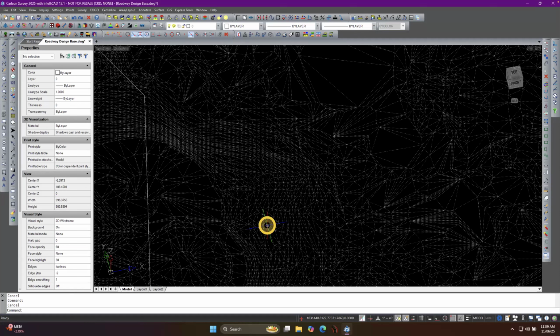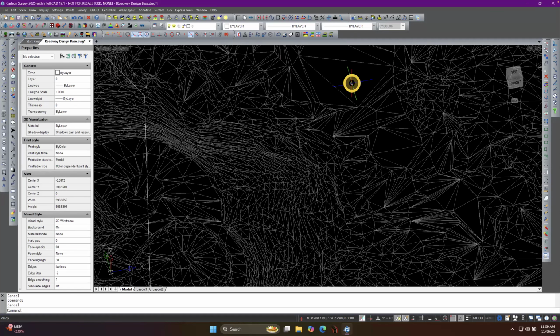And those of you who might be new or recently in the terrain modeling world, terrains are typically represented by all of these triangles that line up edge to edge and form this contiguous blanket of material based on these little triangles that again match edge to edge to edge. And they're all triangular because a triangle represents the minimum number of points that you need to define a plane or a planar region in three-dimensional space. It takes at least 3 points.